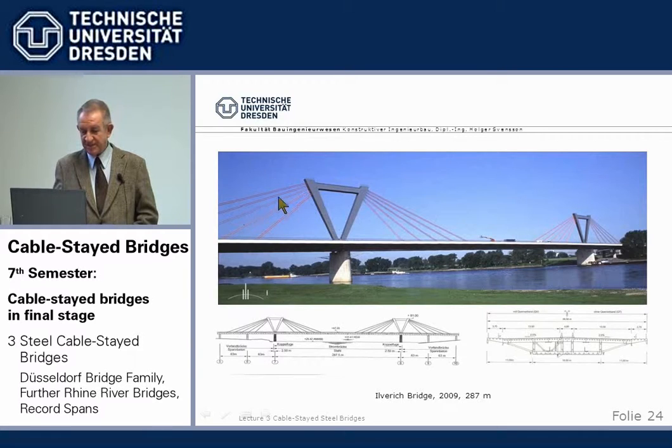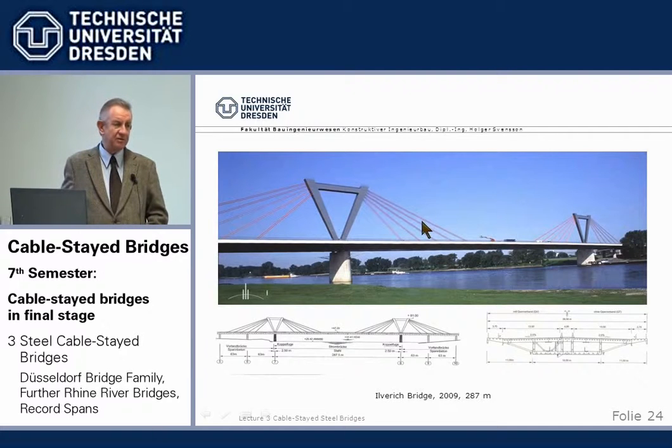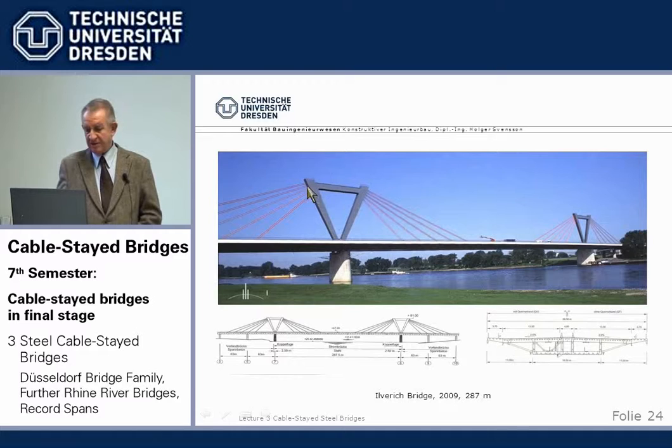So instead of having the cables up like this and a vertical tower, since this height was only permitted and the cables need a certain minimum angle to have them economic, the tower was split in a longitudinal V and here connected. So we have basically the same forces in the stays, and here we just tie them together.